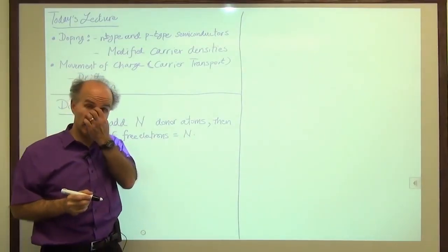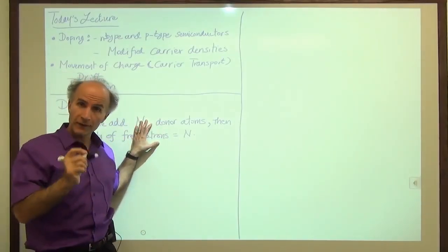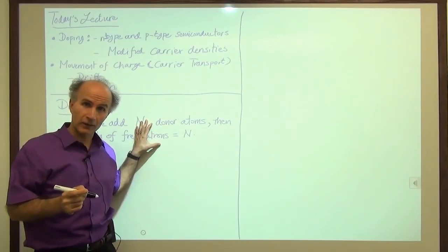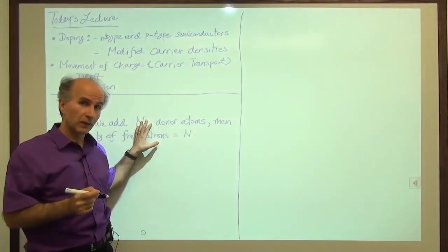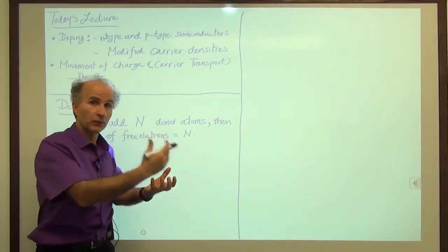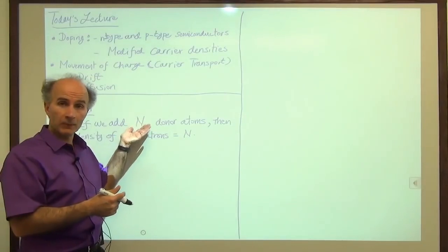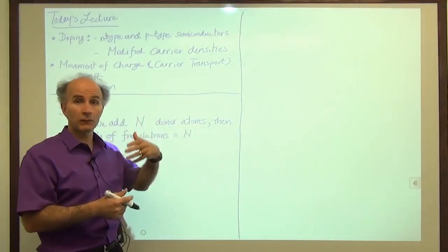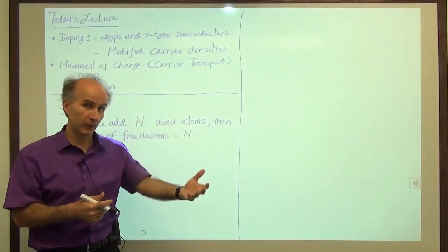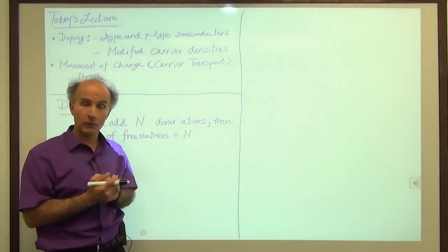It's a little strange because before doping, for the intrinsic, for the pure silicon, we already had free electrons. So shouldn't we add these two, Ni, the number of free electrons for the pure silicon, and then this many donor atoms, this many electrons for the addition, for what's contributed by, for example, phosphorus atoms? Well, we are making one assumption here, which is actually very good in practice.